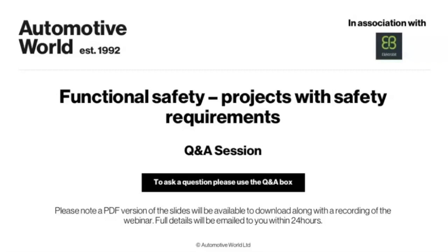That would be the same for the application. So if you have a QM application residing in the same partition, in the same memory context or memory space as your safety functionality, you need to make sure that there's non-interference. And for the higher ASILs, C and D, I think there's no way around using memory protection.